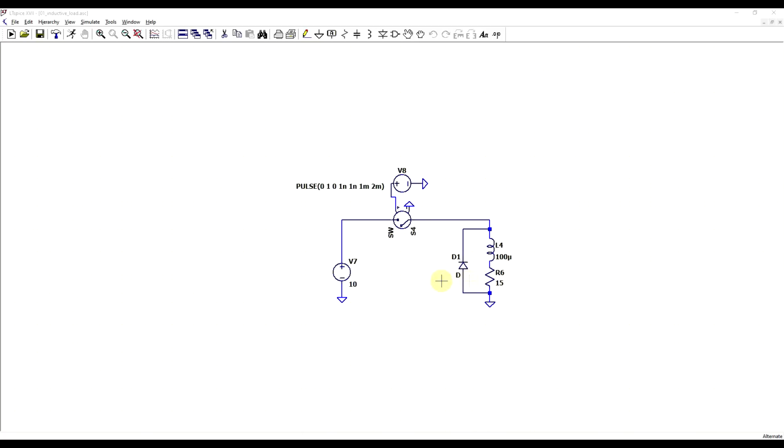Today I will check the following. On the semiconductor side, a basic diode and a transient voltage suppressor, and on the passive side, a basic resistor, a varistor, and an RC network. First thing to use is a basic diode. When the switch turns off, the current running through the inductor will close back through the diode. This is also sometimes called a flywheel diode.